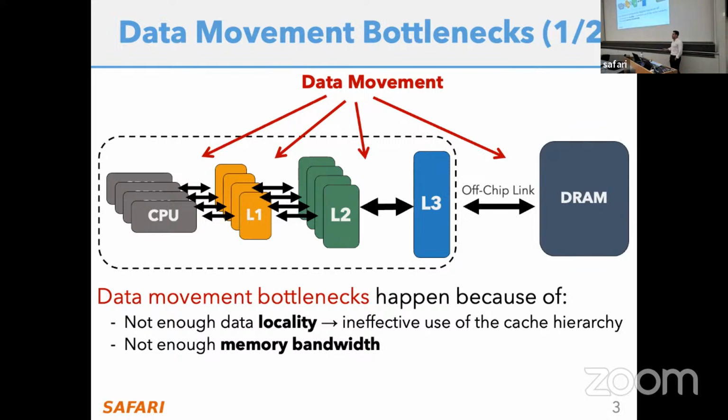Your memory device or storage or your caches might not give enough memory bandwidth for your application so that you can maintain high compute throughput for your system, or maybe your trip latency to go to main memory or to the storage, when you sum all of those latencies, is too high, and then you cannot mitigate this data movement bottleneck.